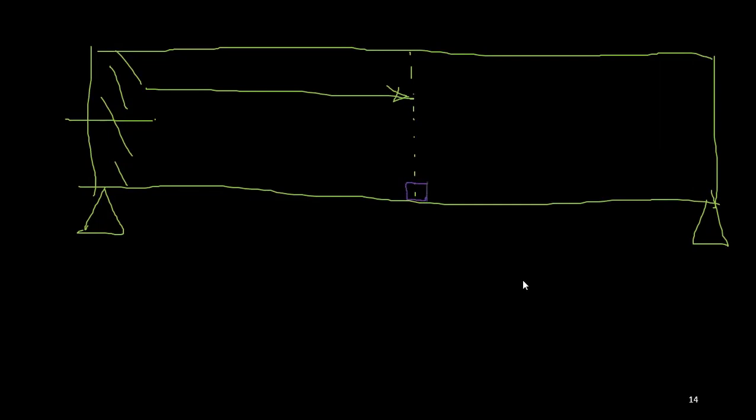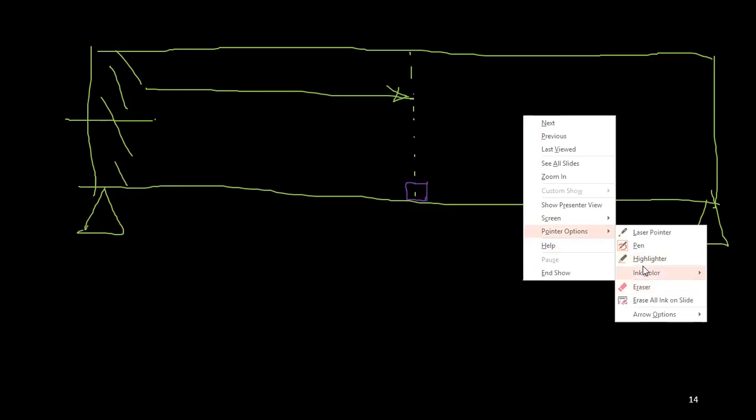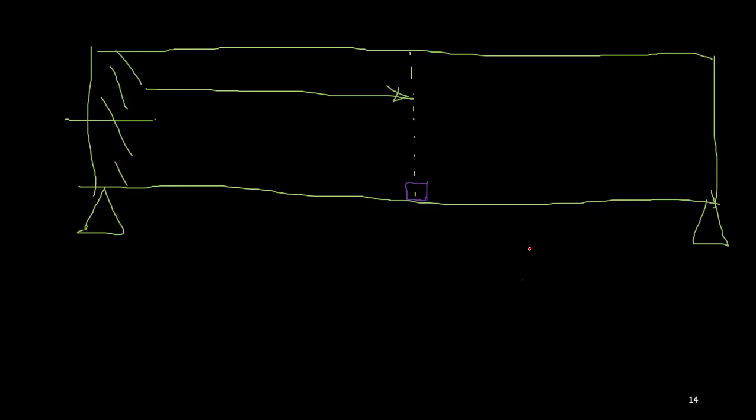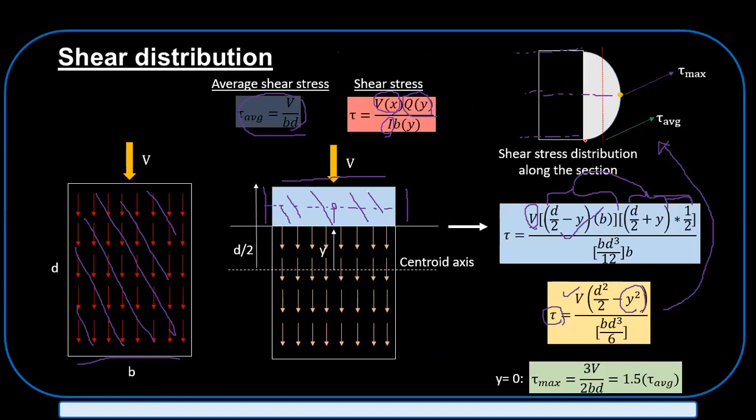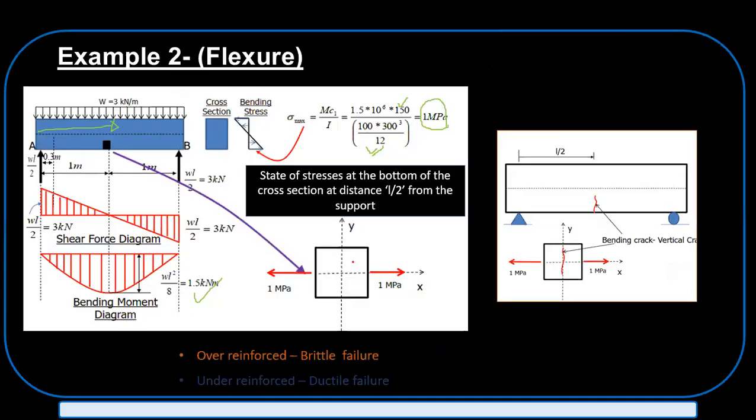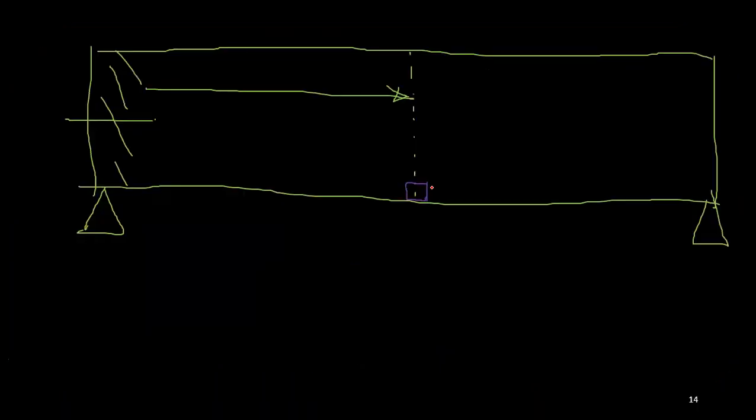So now the fundamentals. What is the shear stress distribution? How does it vary with height? You remember shear is almost zero at the edge fibers, that is, the bottommost and topmost fibers. So that means this element does not have a shear contribution, right? It will only have the bending moment, compression and tension.